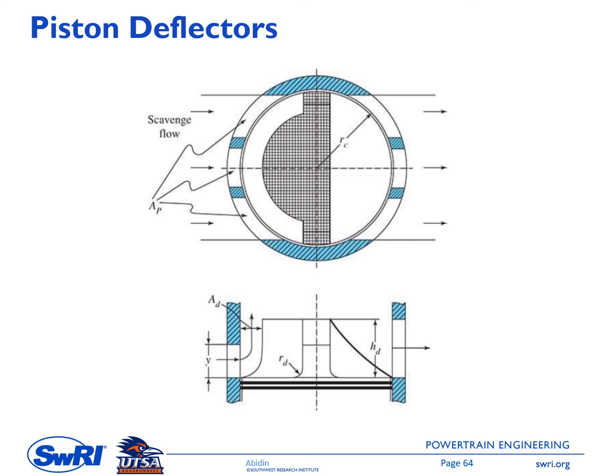This figure is showing a configuration of the piston. So they call this a piston deflector. As I mentioned to you in the previous slide, it is intended to improve the scavenging process. So as you can see in here, we have a unique feature of the piston. Let me put a red color here. So this is the unique feature of the piston. Because of this unique feature, the fresh mixture entering the cylinder chamber gets deflected and moves up instead of, let's say, straight to the right. So with this flow deflection, it will maximize the scavenging process of the exhaust gas.